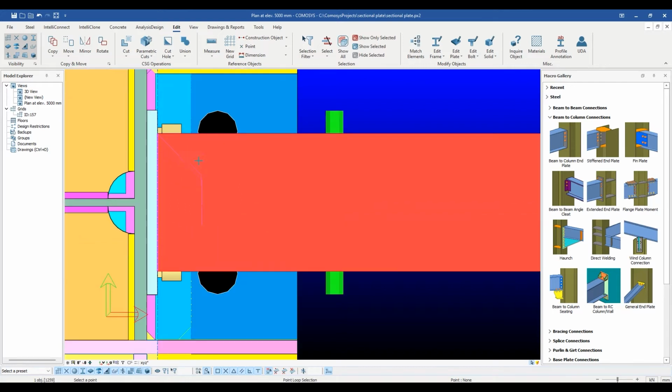After selecting the part which needs to be cut, the user needs to select some points. These need to be at least 3 in number. In our case we need 4 points. 2 are directly snappable on the part itself, and the other 2 can be snapped to using direct entry techniques. So no need to create these points. Just select them and then select the first point again to finish the selection.